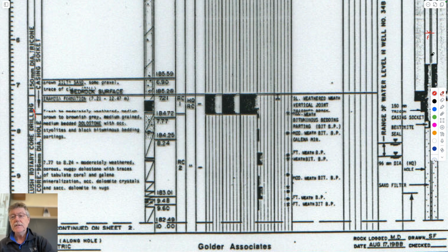And then what you can do in this, once you've got everything settled down, is you just pour water down this tube to raise the water level by some amount, and then you plot as a function of time how that water table drops. So you raise it up to here, you get a certain height, you wait for 10 minutes, it goes down, you wait for 20 minutes, it goes down some more. The rate at which this goes down is some measure of the permeability or hydraulic conductivity.